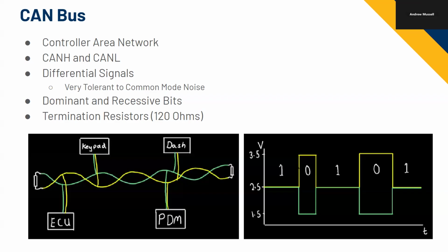But at the 1-bit level, where they're at like 2.5, how is that 2.5 volts? How's that voltage conserved? Oh, that's actually a good question. I'm not entirely sure of the answer. I think things are just driven to a common mode when they're not powered. Like they have a reference pin that they just power to a common mode. And I know that it stays at 2.5 volts because if they're both at 2.5 volts, there's no current drop across this resistor, so it's not driving them to any other level. But yeah, that's a good question that we should look up in the CAN transceiver data sheet.